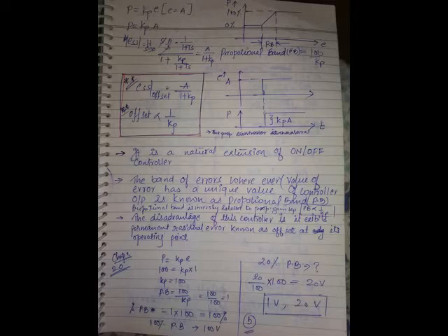To check mathematically, we know that for any system, when you subject that system to sinusoidal input, output also will be sinusoidal. But the output will have different magnitude and different phase. Suppose if the output is exhibiting phase lead characteristics, what does it mean? Fast response.